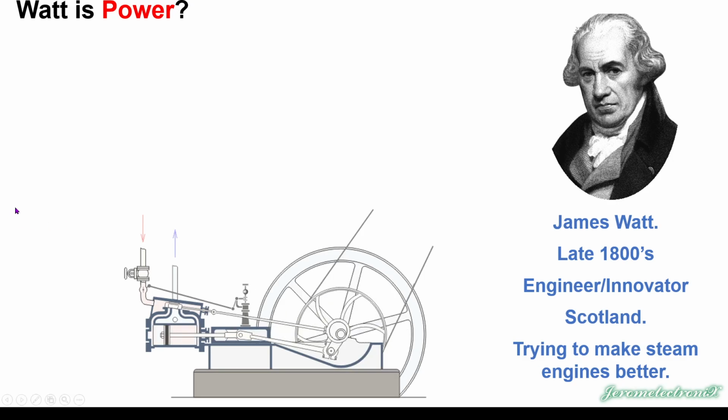And just think, we've got a sealed pot of boiling water somewhere off to the side, and it's emitting steam, and steam's going down this pipe, and we can increase or decrease the flow of steam with this valve. But there's another valve below that one that is actually controlled by this whirligig right here. And just like when you hold your arms out when you're spinning on a chair or spinning on the ice, you slow down, but when you pull your arms in, you go faster. Same thing. These are heavy metal spheres here.